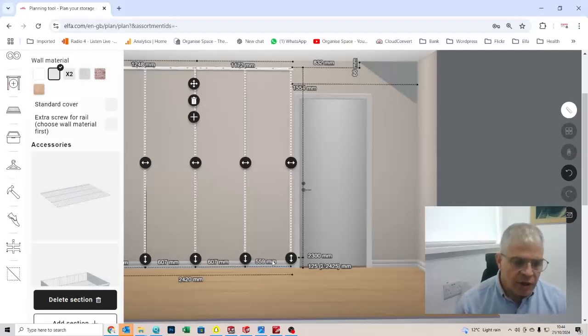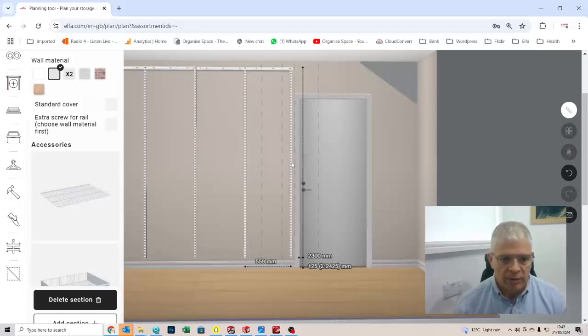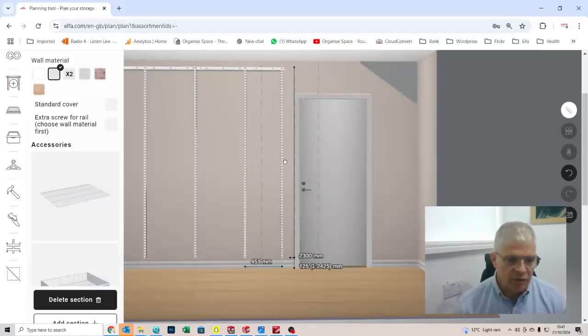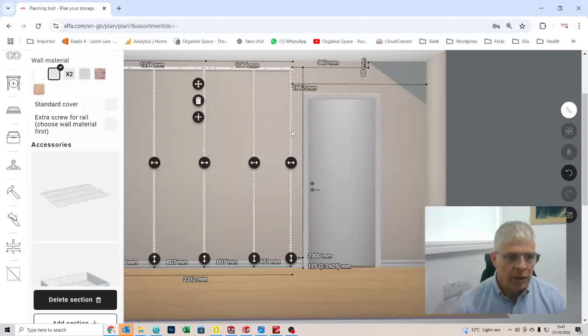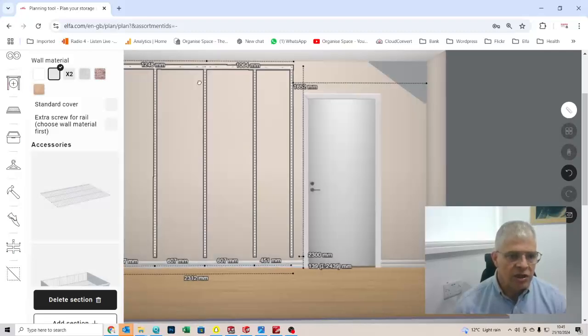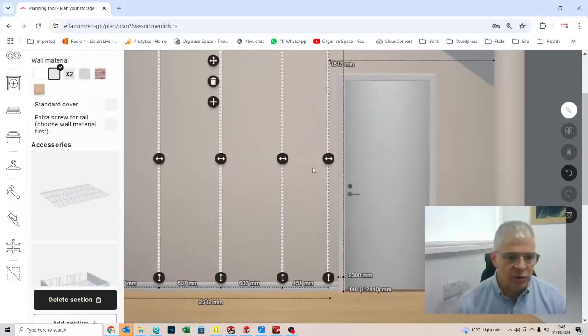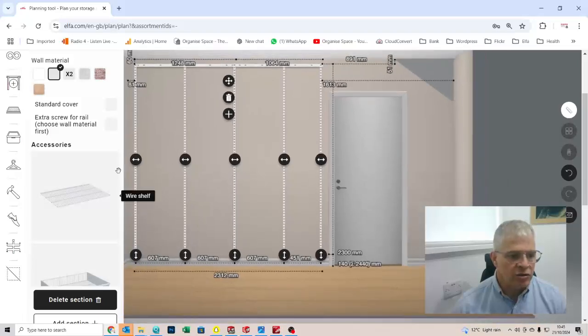I'm not going to be able to fit gliding components into that bay. I won't be able to fit shoe racks or baskets into that bay. So I'm going to drag that back to a standard bay size, 451, it clicks in, and then I'm going to recenter my whole assembly nicely between the architrave and the left hand wall.